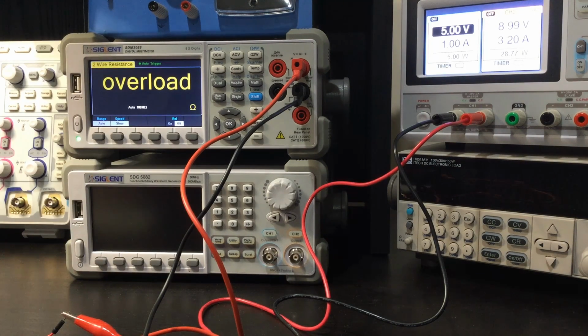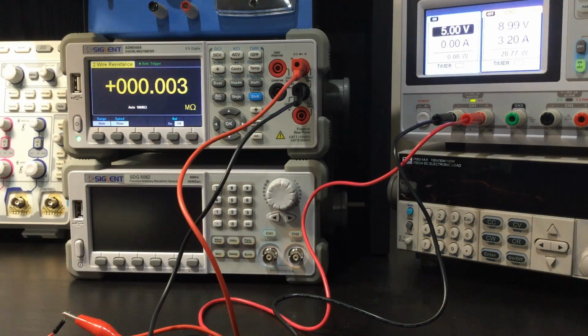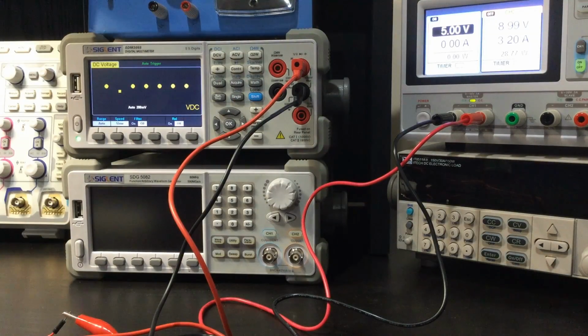I didn't use a 1% resistor or 0.1% resistor as we specified, which would have got us much closer in terms of voltage. Anyway, we'll go back to measuring the voltage across the load. Power on. And switch back to DC volts. And what we could do, if we were building this for real, given that we've got that resistor, we could tune our adjustable resistor or use a potentiometer.